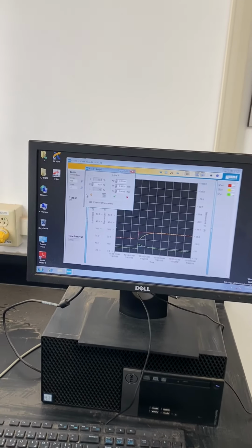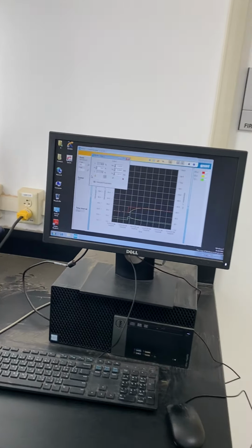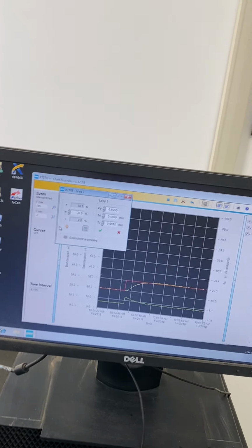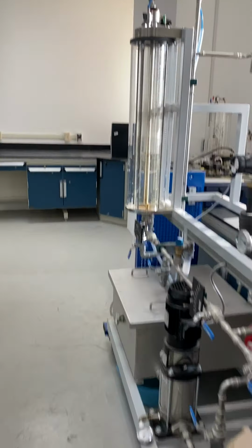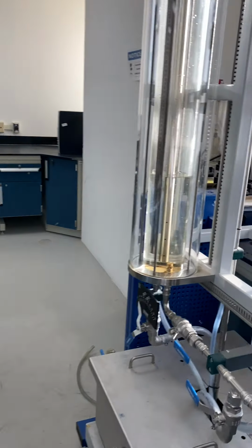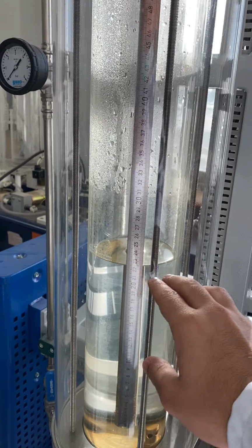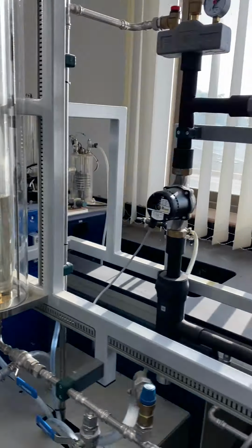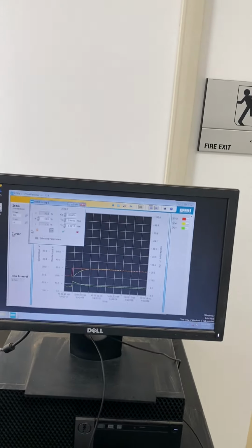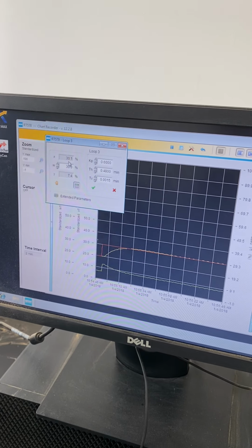As far as I remember, guys, the level sensor was showing a little bit of fluctuations in the past. So we might notice that the process value will keep fluctuating up and down by somewhere around 0.5%, plus and minus 0.5%, going up and down every little while.